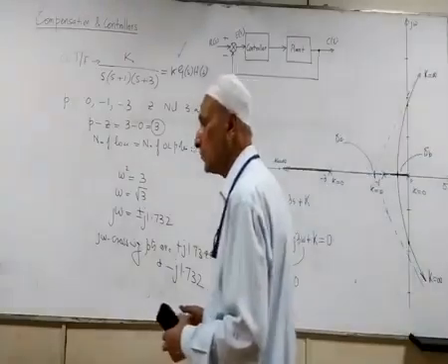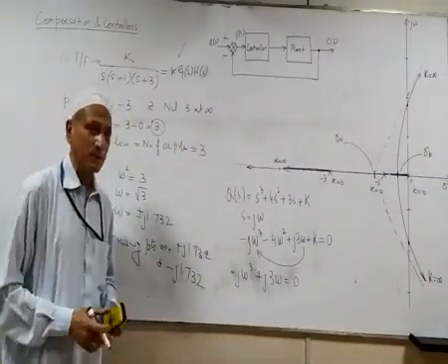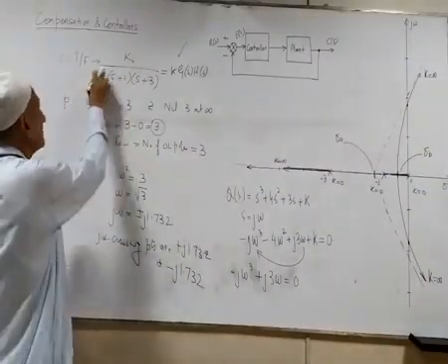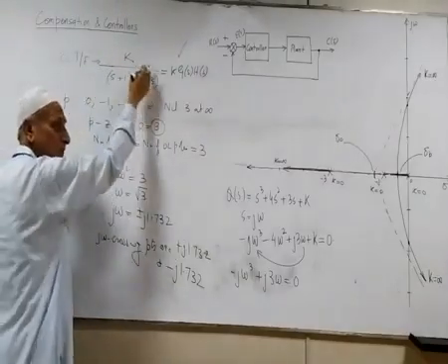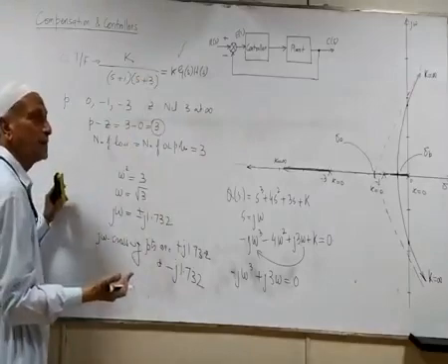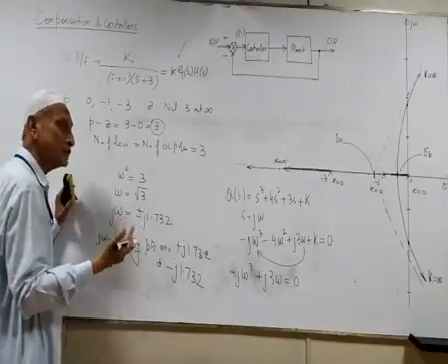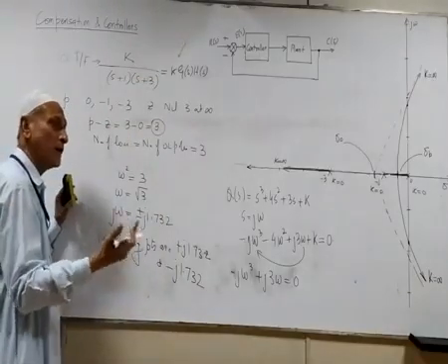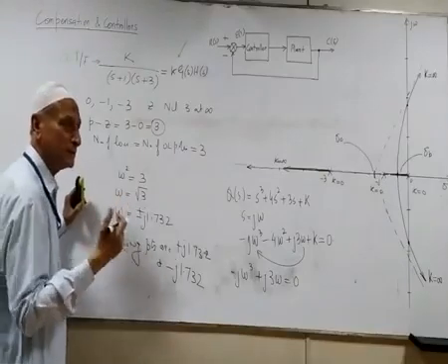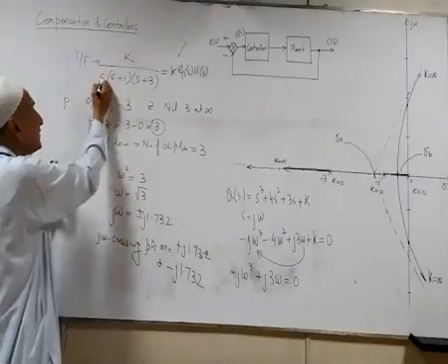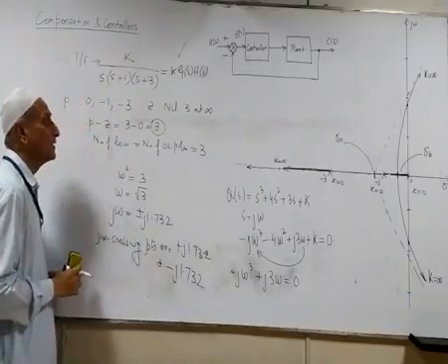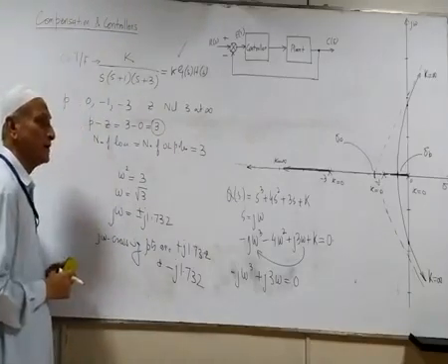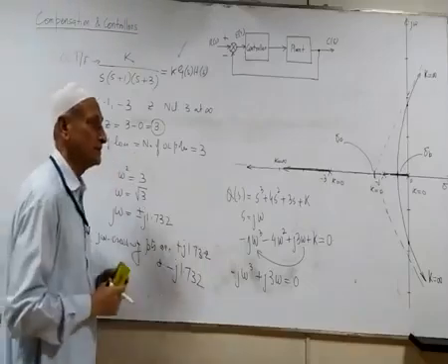Now compare this root locus with that of example 3, the system which does not actually have the pole at s equals 0, which was this one. That was a straight vertical line and it was a stable system, an all-round stable system. But then when we have incorporated a simple open loop pole at the origin, the scenario completely changed.